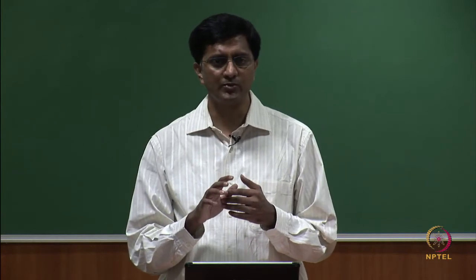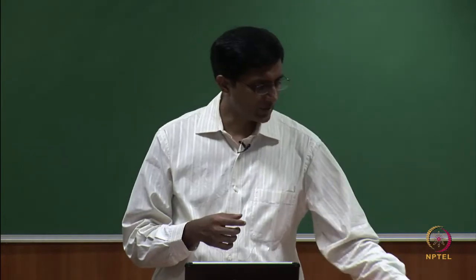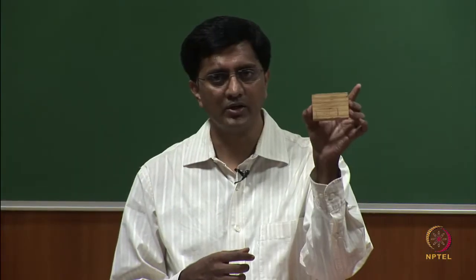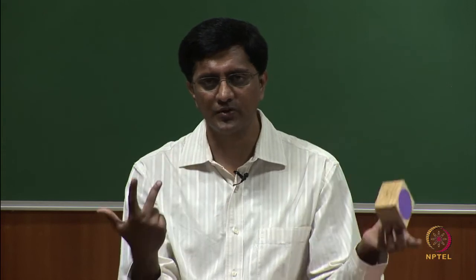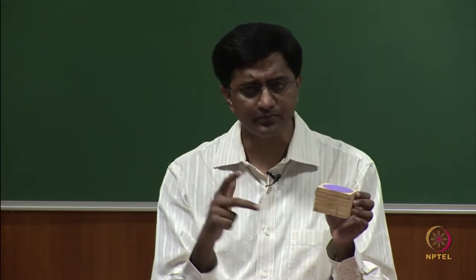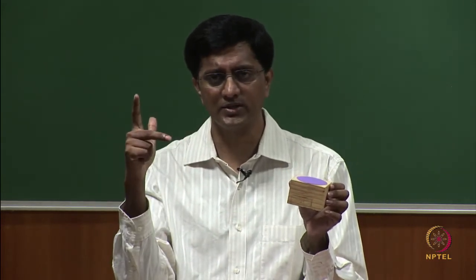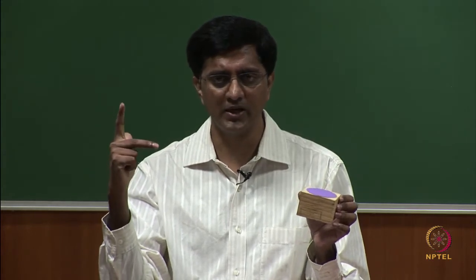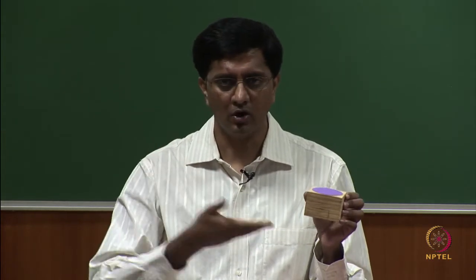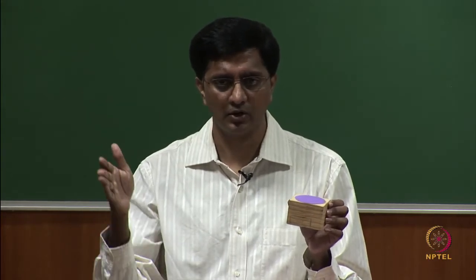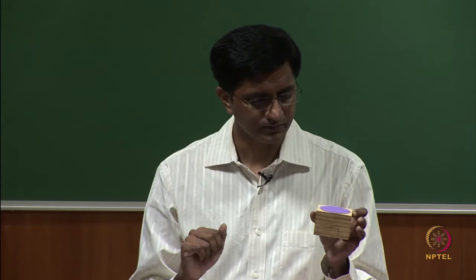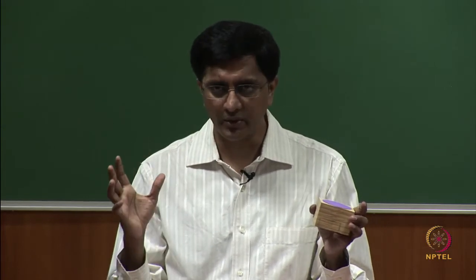What do I mean by principal planes? We said the object is in space and we define the object in space using 3 axes. Because we are using the Cartesian system, these 3 axes make 3 different planes: the horizontal plane, vertical plane and the profile plane. So, these 3 planes are perpendicular to each other.